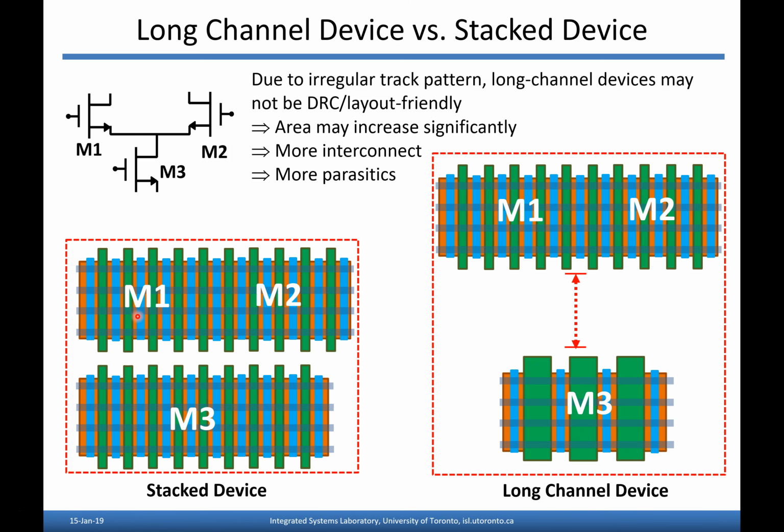But there's a problem. Here's a typical scenario where you might, as an analog designer, want a longer gate length. A nice simple situation is where you've just got a diff pair and the tail current transistor M3. That transistor doesn't have to operate at high speed. I want it to have a high output impedance, so I'm going to make it have a longer gate length. The problem is that M1 and M2 are maybe a high-speed diff pair, or you would like it to have as high a gm as possible. So those are minimum gate length.